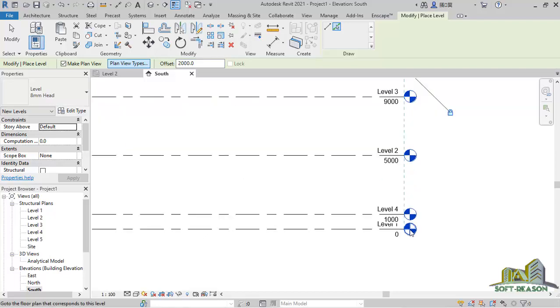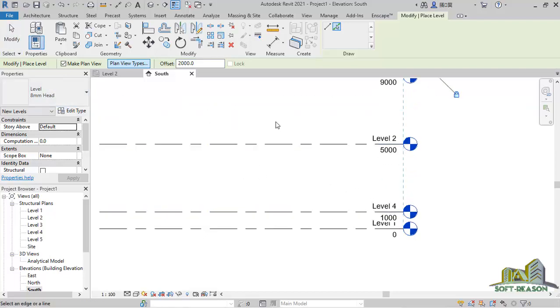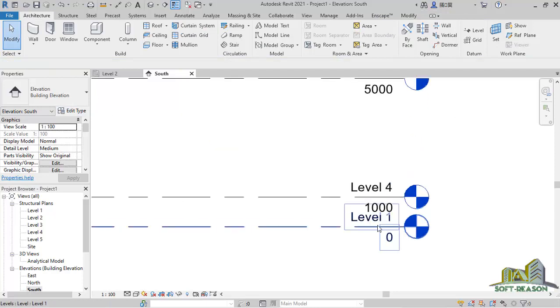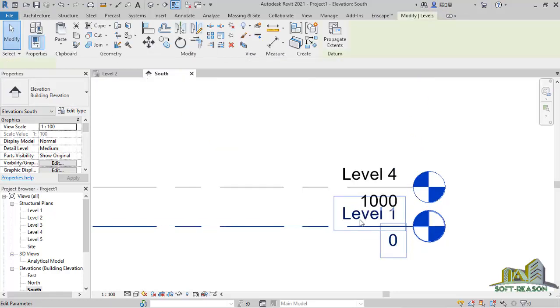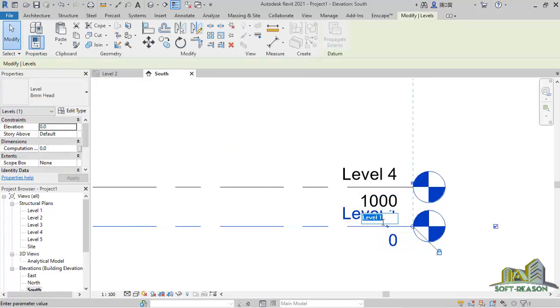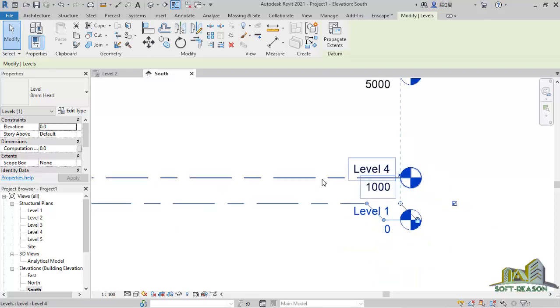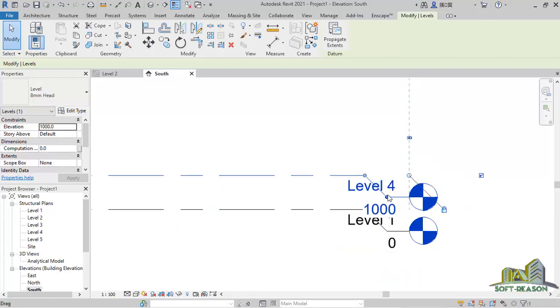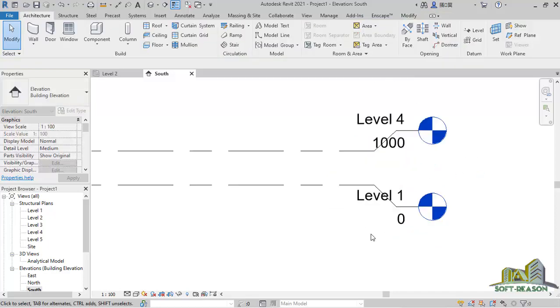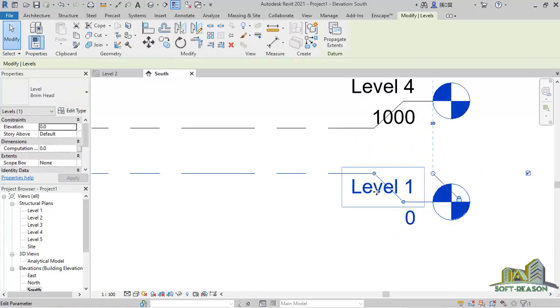So now I want to edit the level. For me to do that, I will deselect this command and then double click here on level just like that. Or I will just click on this, be able to hold down on this elbow, alright, to shift it so that it will not mess up the whole thing. I'll hold this one, pull it up just like that. I'll click on this level to change it. This level I will call it 0F,